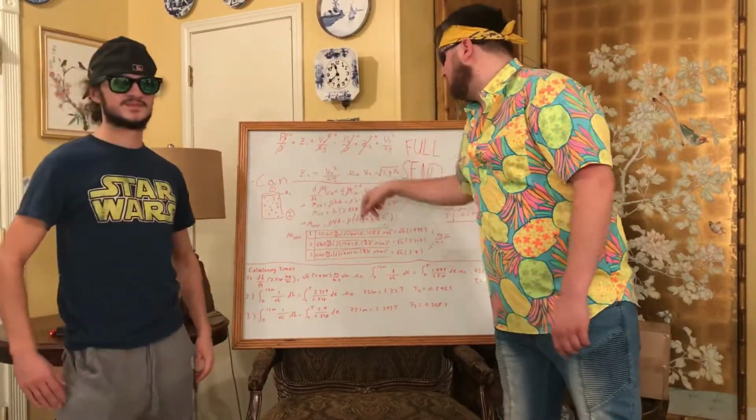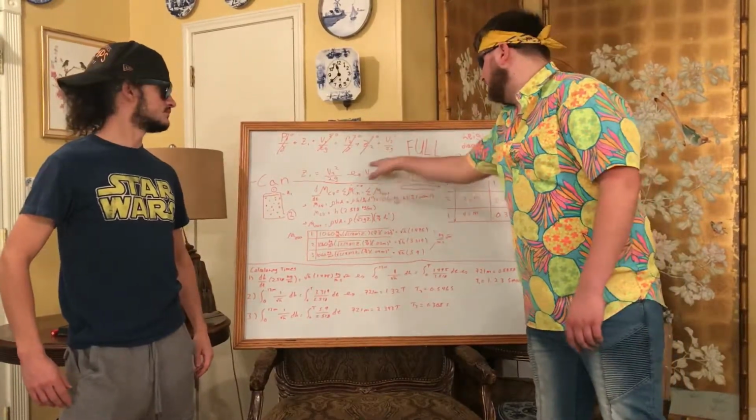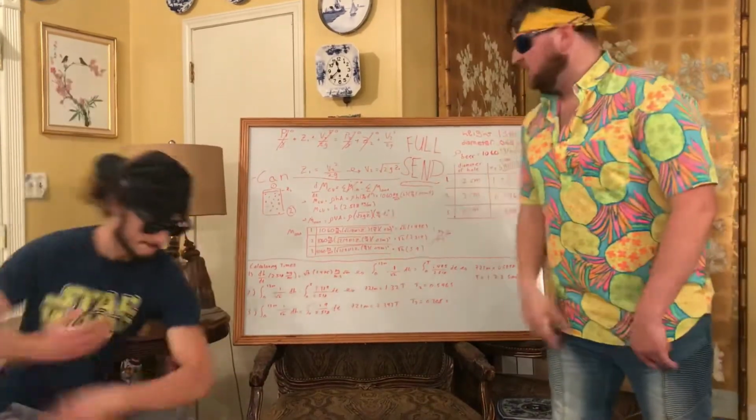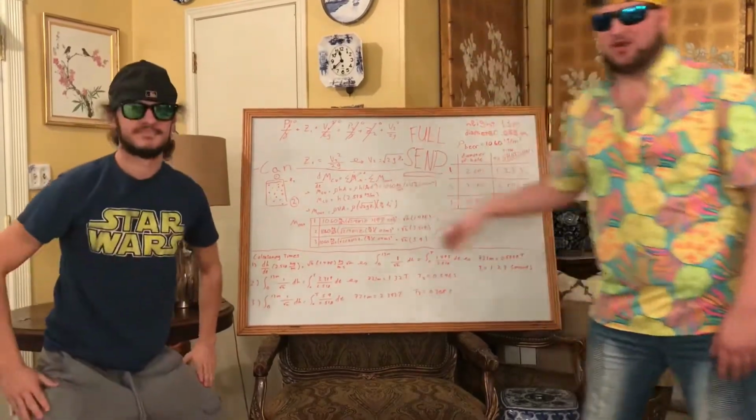So you got Z1 equal to V2 squared over 2g. Whenever you rewrite the equation, you got V2 is equal to the square root of 2g Z1. Now I'll pass it off to Brother Payton to explain the conservation of mass equation. All right, bro.